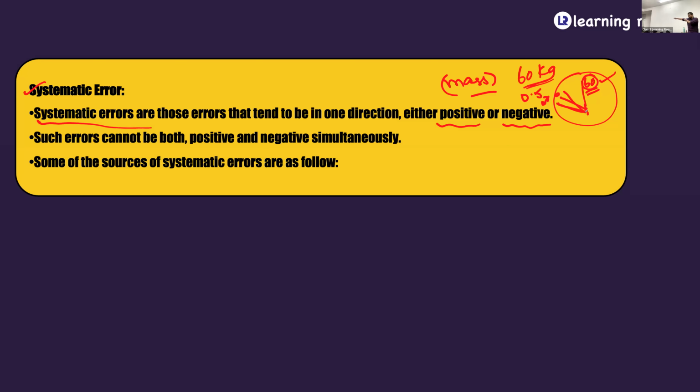Yesterday I went to actually buy a weighing scale for some experiments. He asked me one question: what is the least value you want to measure? I told him 25 grams. What I wanted to do is take some powders and prepare a small experimental kit. Let's say I want to put 10 grams of baking powder into something. I need a device which will actually measure 10 grams. Now with 25 grams, what is the loss I'm going to face? I cannot measure 10 grams because the least value itself is 25 grams.